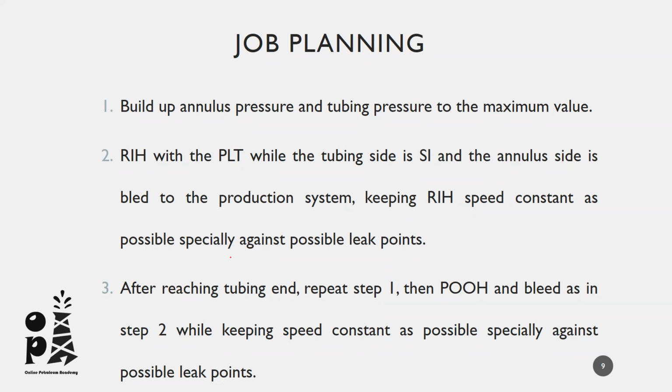So how can we do this in an offshore gas lifted well? One of the possible options, this is not the only option we can do, there are many options you can do depending on your well and the situation and the availability of the pumping equipment and something like that. But in our case, we have gas lift on location, so we can build up pressure using the high pressure gas source. So in order to force flow through the leak points, we make the following sequence.